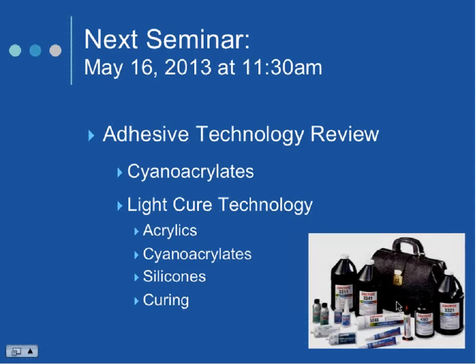And sometimes heat, even with our acrylics, you can give it a little bump of heat and that'll get it there faster. Not much you can do with cyanoacrylate. You just have to wait for that 100% cure. And we do recommend that you don't move parts while they're still forming at fixture time.